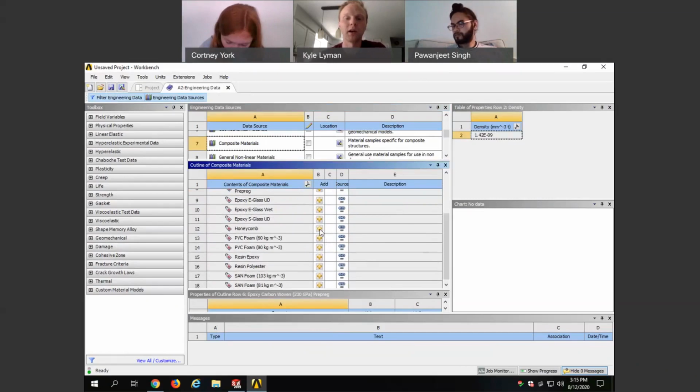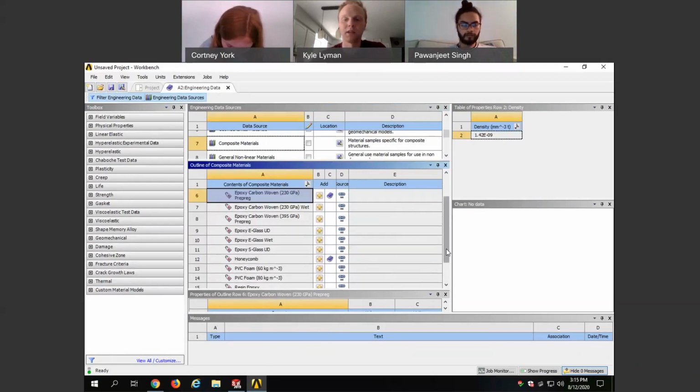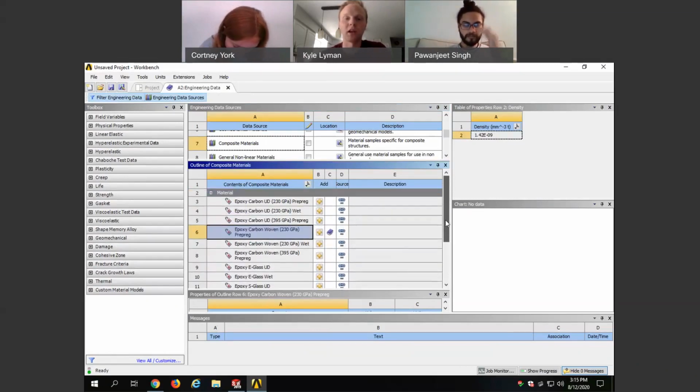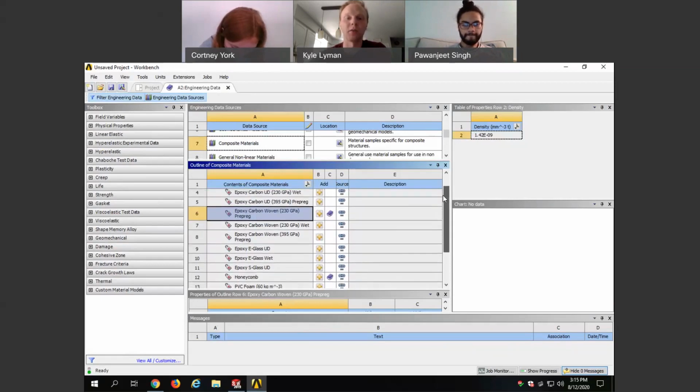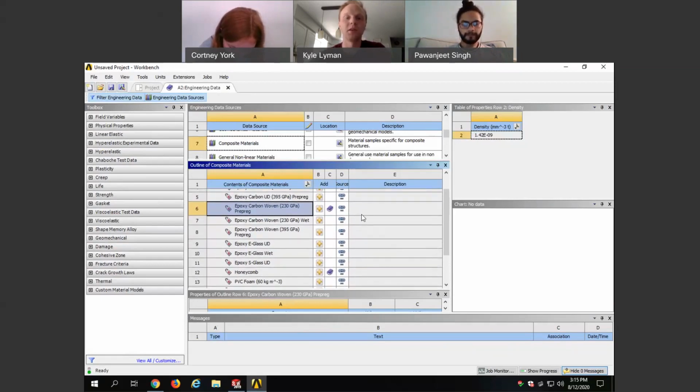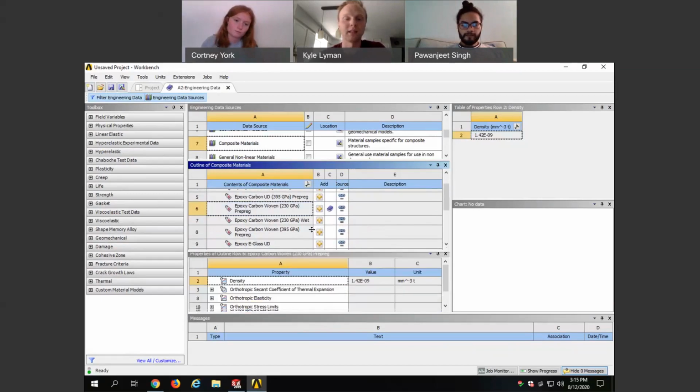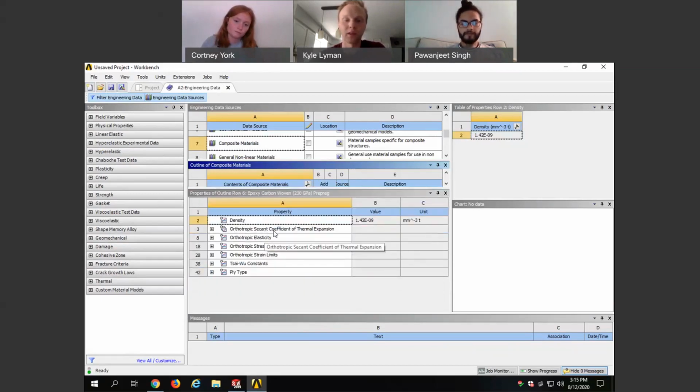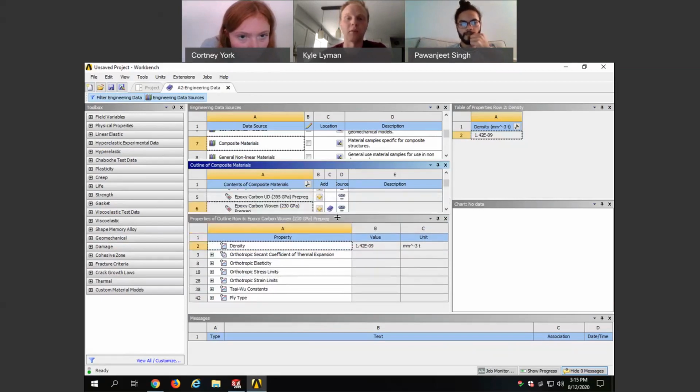So honeycomb, we're going to go ahead and add that. It's really important to know that these are generic values provided by Ansys, and this by no means represents every single carbon fiber in existence. There can be carbon fiber that meets these criteria but also has different densities, elasticity, stress limits, strain limits, etc. That can all vary depending on the brand of carbon fiber that you buy.